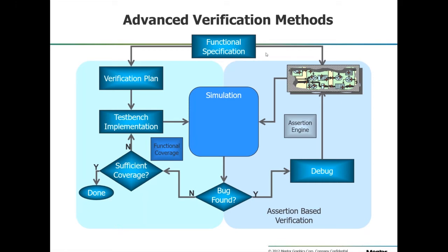But what we can do here now is say, for every one of these features, or for every one of my test bench objects, I have these 4 assertions and other coverage-type objects, and if those things are activated and never fail, then this requirement is covered. The next requirement is maybe these 3 coverage objects, and if those are tested, then that is finished. And so it becomes a measurable thing where I can say, I've got enough coverage, I'm done. So that was functional coverage.